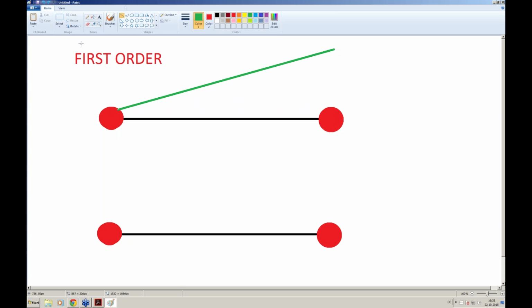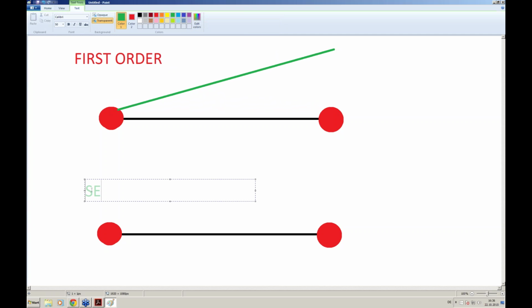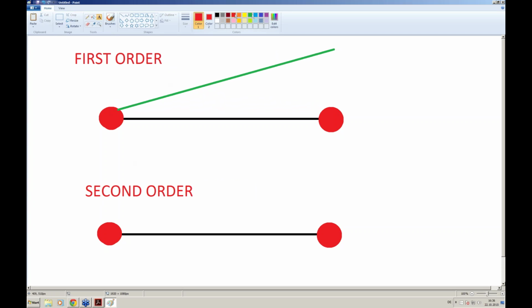And with second order, we're using a kind of spline interpolation between the points. So a second order mesh, and that's in the end the lesson which I want to give you right now, is more accurate with the same number of points.